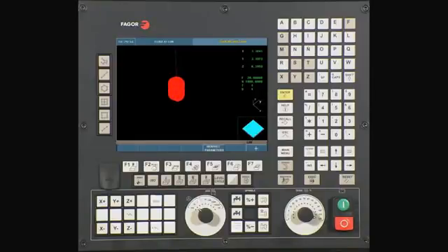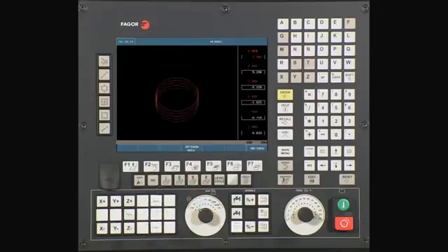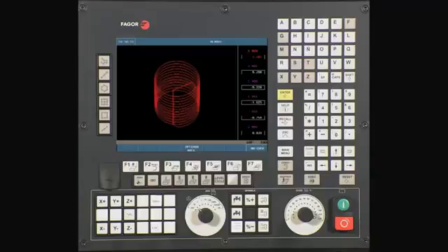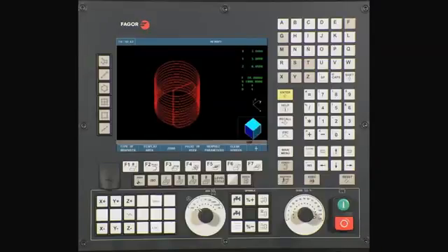If the graphics are too small, press Display Area and select Optimum Area. The CNC will then automatically adjust for best graphic view. Confirm that the cycle has finished with no errors. You are now ready to save or execute the cycle. To execute the cycle, press Escape 2 times.